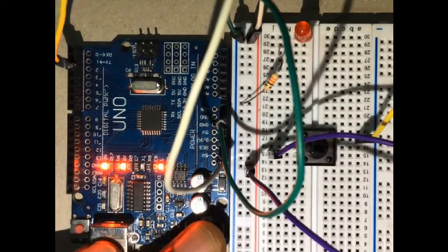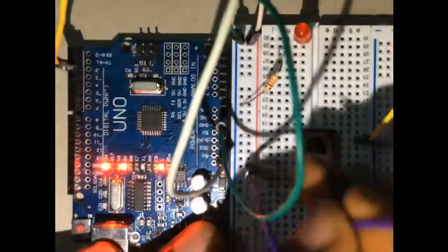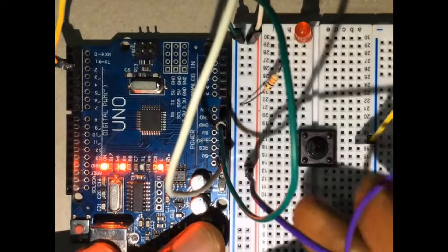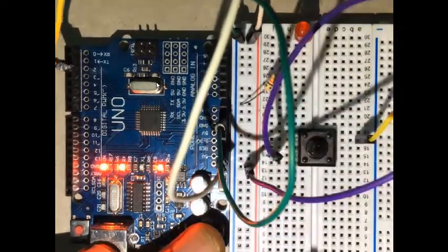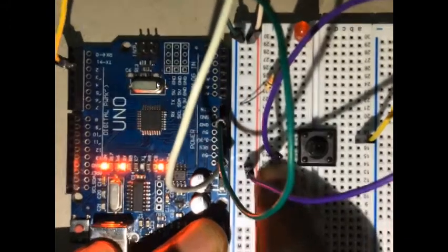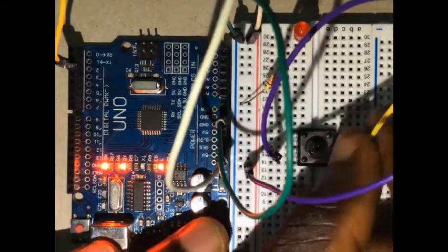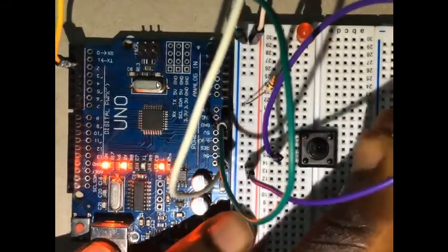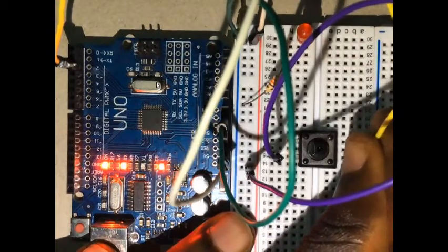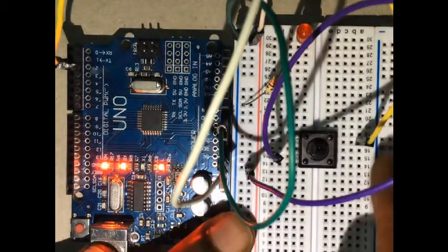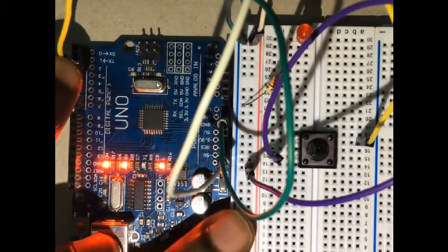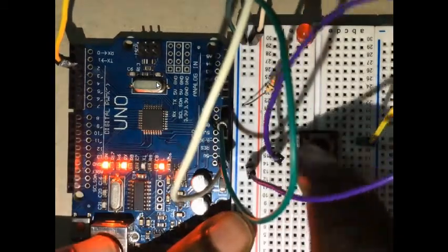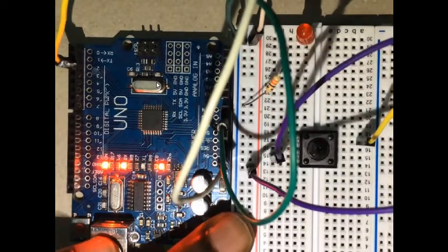So when we connect 5 volts, you can see that this purple wire connects to the 5 volt rail. When we connect it to one end of the button, we have connected that end of the button to 5 volts. And when we connect the other jumper wire, the yellow jumper wire, to our digital pin 2,